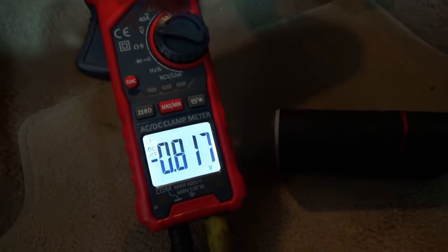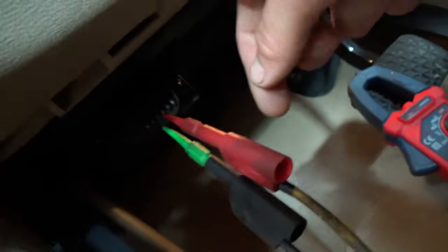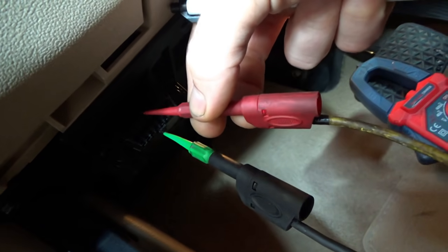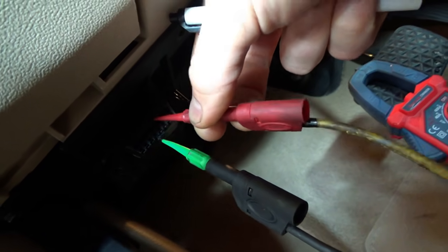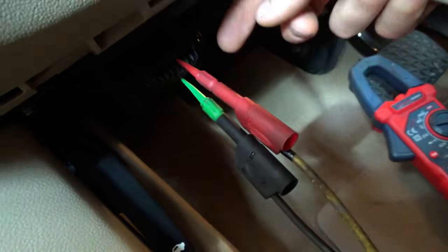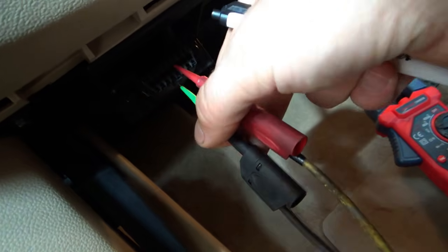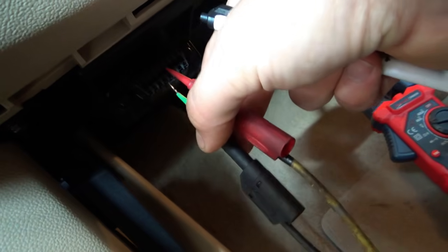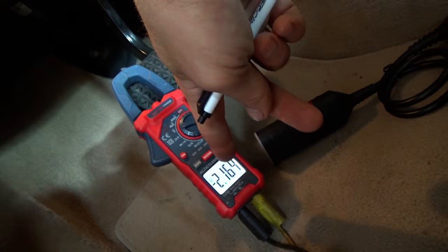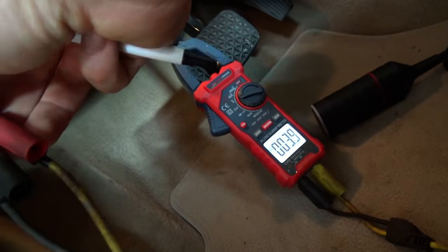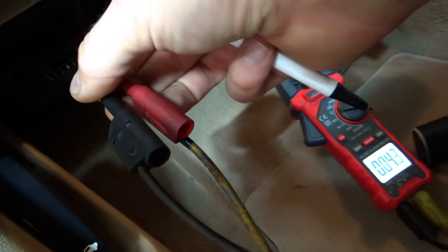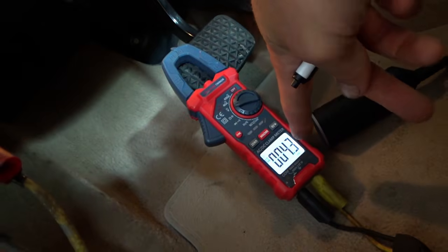So you want to start with the voltage measurements. Let's measure from pin 12 to ground. So pins 1, 2, 3, 4, and 5 are going to be grounds. Look at that. We have 3 volts on this network wire right now on pin 12. What about on pin 13? Oh, did it go to sleep? It's showing 0 right now. Right as we're measuring, the car might have timed out. Now we only have 4 millivolts.